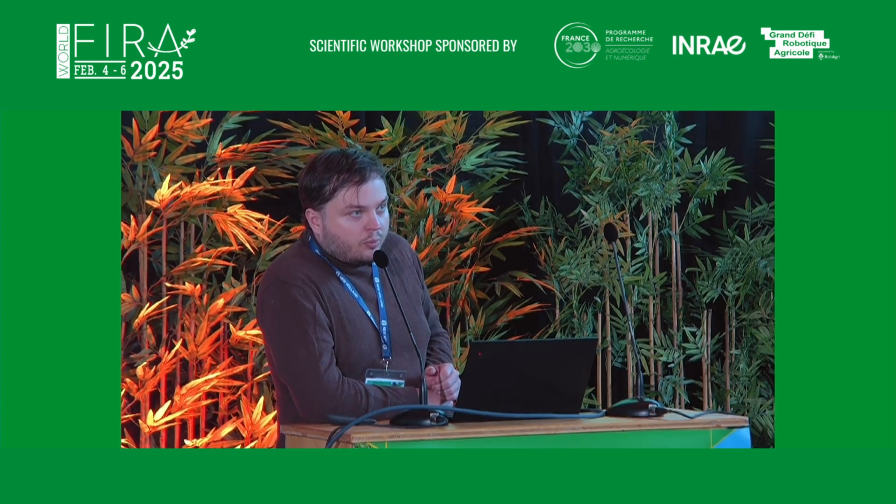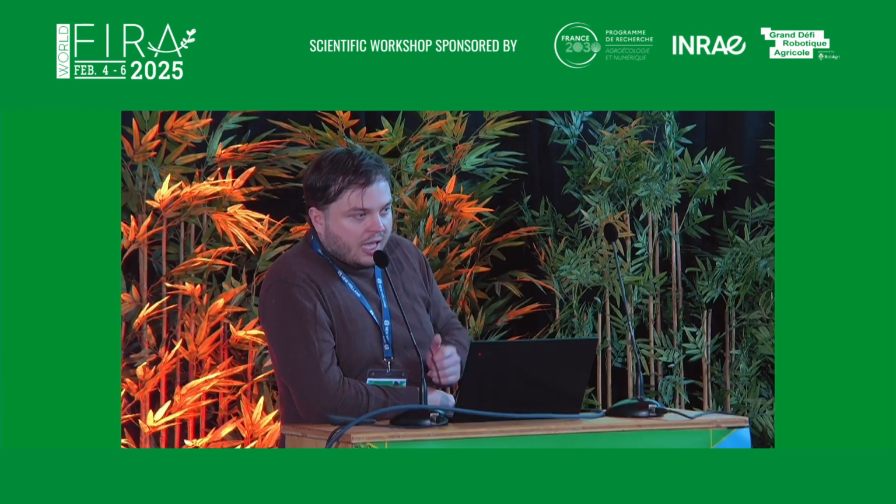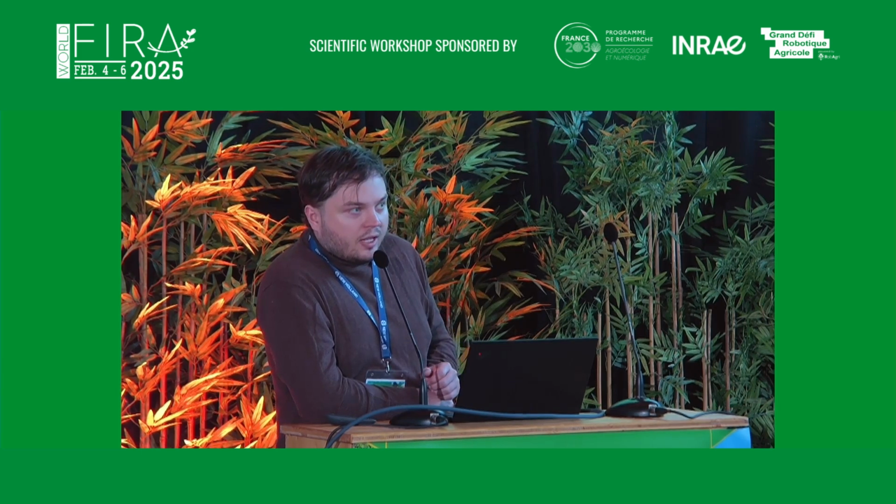We solved this also in part in simulation. My colleagues developed some really nice LIDAR simulations, for example, that take this into account. So we can directly simulate this LIDAR relatively physically correctly, and, for example, judge how this dust will affect us. And regarding the precision, that depends, of course, on the application. But for the vineyard one specifically, we're talking centimeters, because the gaps between the plants aren't that large. It's basically maybe twice the width of the vehicle.